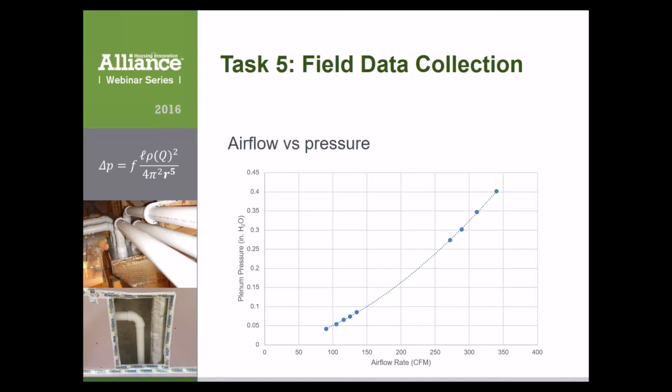If you look at the chart here, we have some measured data and then an interpolation line. We see that the static pressure, even when we're talking about 300 CFM, is only about 0.35 inches of water. So in general, this is under half an inch of water, which is much more reasonable for a typical system, and isn't extraordinarily excessive, like an inch of water or something.